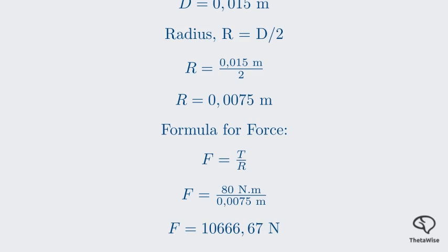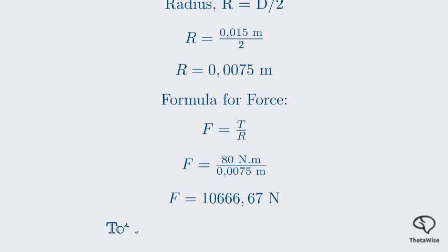When a drill bit cuts, it exerts a force in 2 directions, creating the torque. The torque is the product of this total force and the drill's radius. Therefore, the total force, which is the sum of the forces on both sides, is 166.67 newtons. Since the question is about the cutting force, this value of 166.67 newtons represents that total cutting force. Let's compare this to the provided memo.